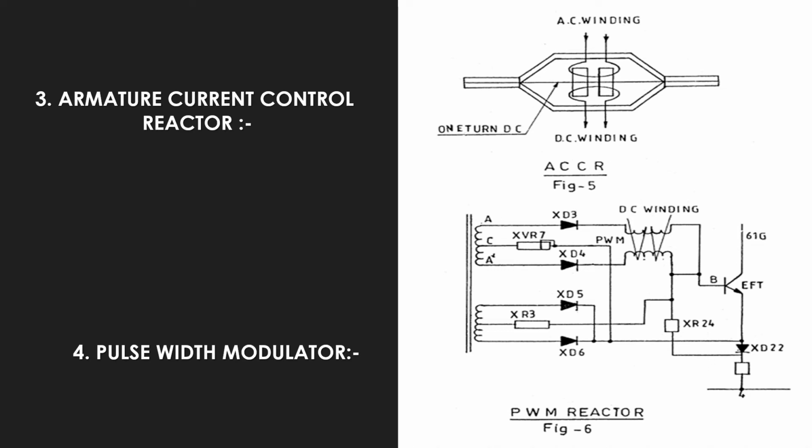Exciter suicide and stabilization winding reduces exciter voltage to nearly zero when the GF contactor is open, and also provides exciter stabilization when the GF contactor is closed. Main excitation control winding, fed from the mixer circuit, turns excitation off to maintain proper load. Wheel slip power reduction winding reduces excitation during the operation of the wheel slip system. 2 other windings are for dynamic braking control, which are not applicable here.